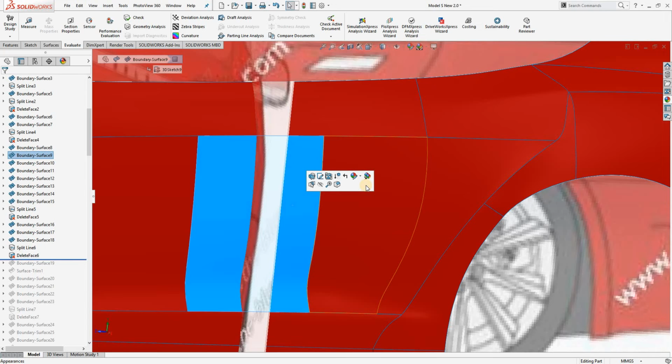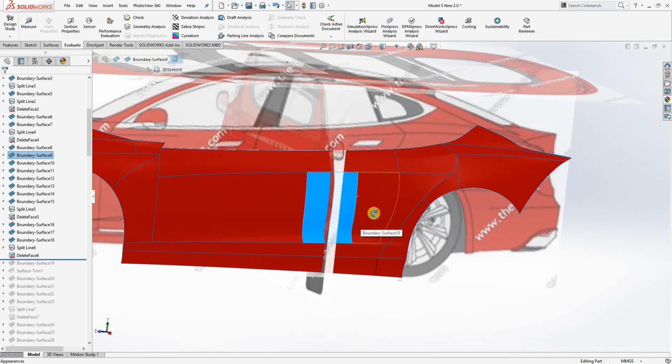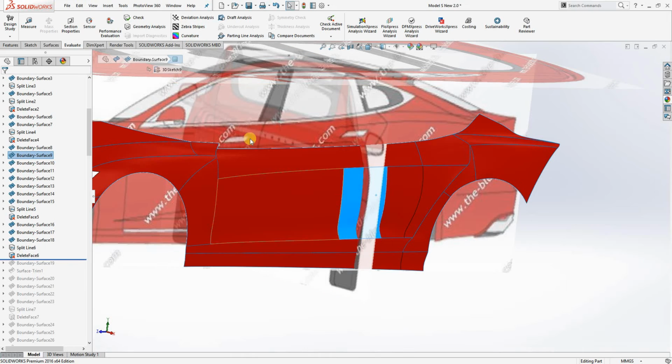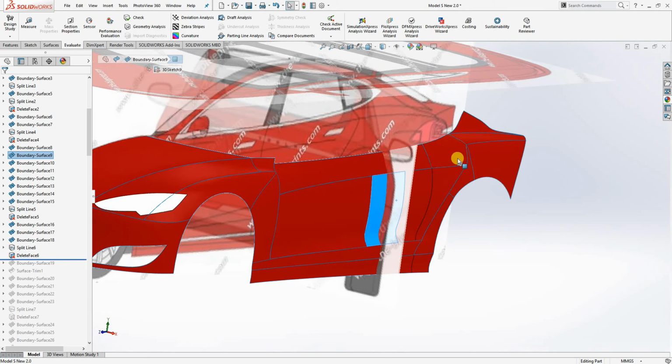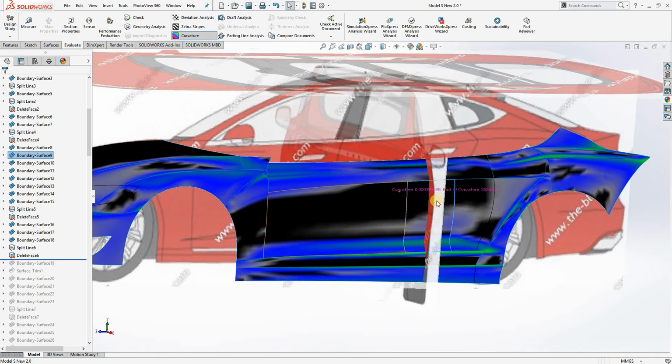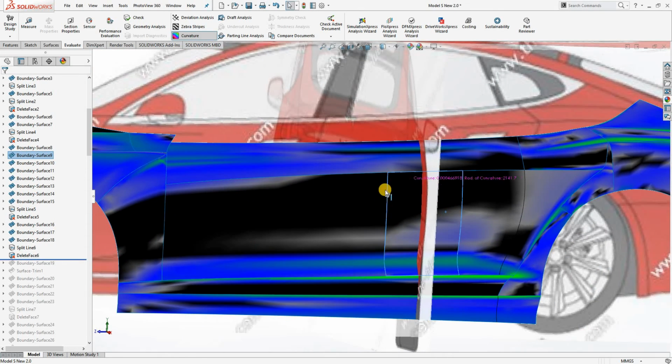Whereas in CATIA or a more advanced modeling package designed specifically for surfacing, you would have a lot more functionality in that regard. So it would be easier to initially create the G2 continuity at all your surface boundaries, and then you would also be able to go back and update the form and shape of your model and maintain that G2 continuity. So with G2 continuity, if every surface was perfect, we would see smooth transitions.